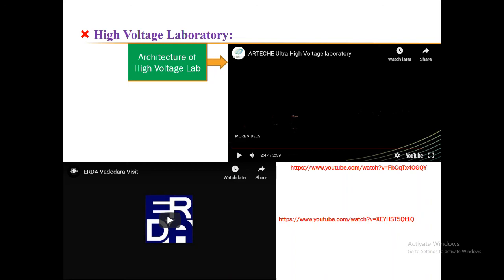Okay, so ideally when we are performing the impulse voltage test, three different types of impulse voltage waveforms can be captured. One is the full impulse, which indicates that the insulation of the equipment is capable of withstanding the applied impulse voltage magnitude. Second is the oscillatory impulse, which indicates internal defects within the insulation, and if the chopped impulse is there, then the insulation is very poor and not capable enough to withstand the applied impulse voltages. So this kind of judgment or decision can be taken by analyzing the captured wave shape.